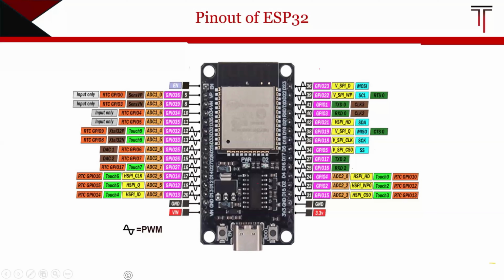Okay. So when coming to the analog pins, these ADC pins are nothing but the analog to digital converters. It contains nearly 18 channels for 12-bit ADC. These ADC pins give us the 12-bit ADC operations. These are used to read the analog signals, and after that they convert them into digital signals, right?